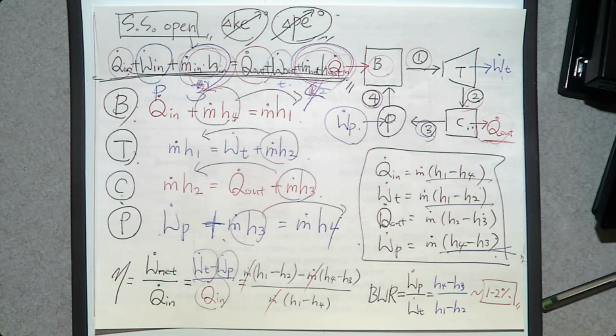Can you go to higher efficiency than that? Yes, if you have a fluid that can go beyond the maximum temperature. So the limitation of this vapor power plant is that above a certain temperature, water cannot exist anymore. That is called a supercritical system. So if you consider only the thermodynamic cycle, the higher the temperature, the higher the efficiency.